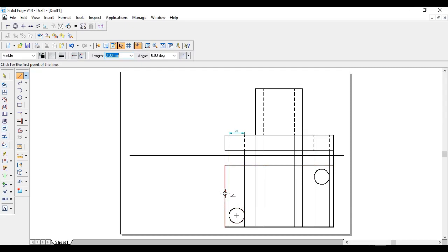This side also you show the middle. Then just move the mouse. Then you can see the middle point. This is the middle. So from the middle, we have to take circle by center point, middle point, and this side is also middle. So circle by center point. Simply you can touch the projection line. When we observe, the innermost projection line is diameter 40. You can just click again from that center. The outermost projection lines are diameter 60. Click it again. So this will be the top view of the given image.